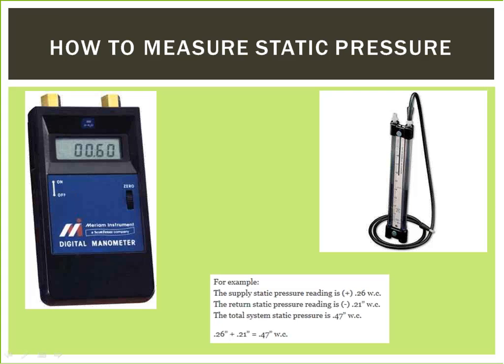Step number 5. Read the return or negative static pressure by moving the tube from the high to the low pressure port on the gauge. Insert the static pressure tip in the test hole on the return side with the tip facing the airflow. Read and record the negative static pressure. Don't forget to insert hole plugs in the test holes when you're done testing.